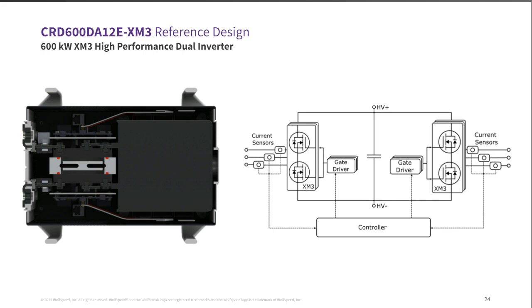So here again, the stack up includes a cold plate, the XM3 power modules, the gate drivers, a controller board once again, and DC bus capacitors and the proper voltage and current sensing on the output phases. So all in a very compact, very high power dense design.